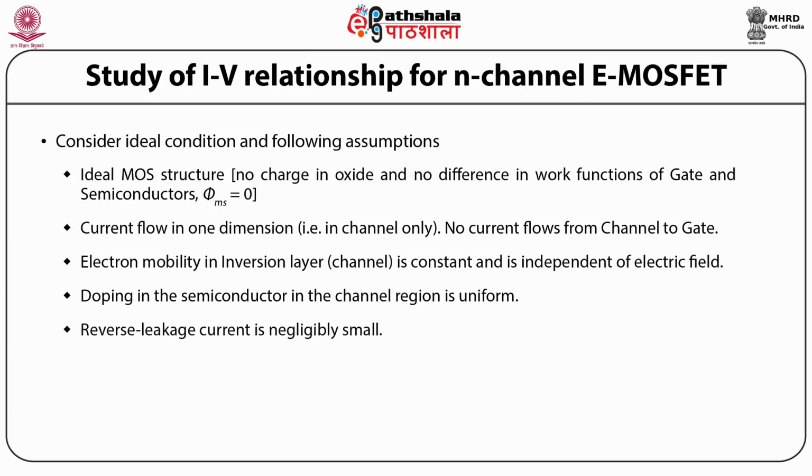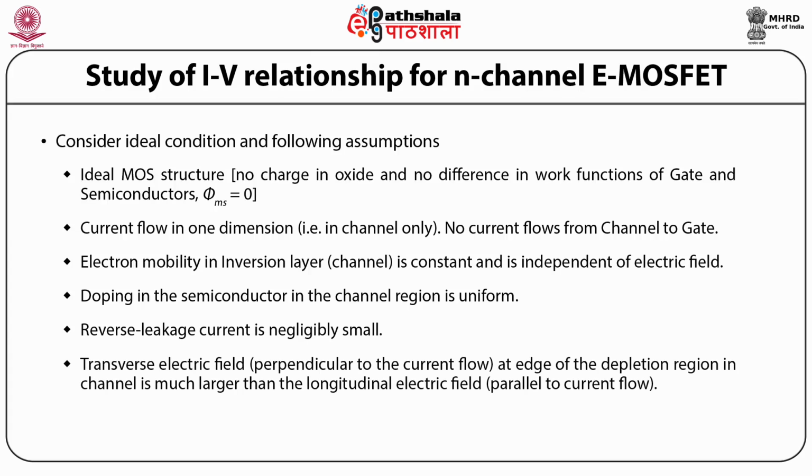Number 4, the doping in the semiconductor in the channel region is uniform. Next is the reverse leakage current is negligibly small. Last assumption is the transverse electric field, which is perpendicular to the current flow at the edge of the depletion region in a channel, is much larger than the longitudinal electric field that is parallel to the current flow.